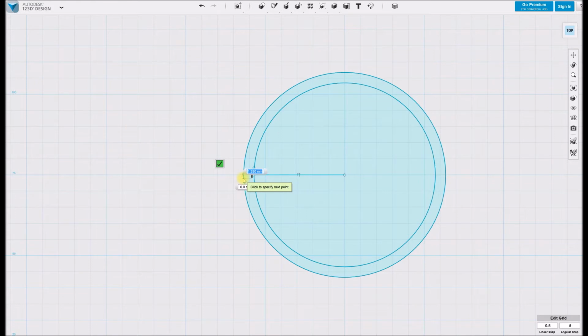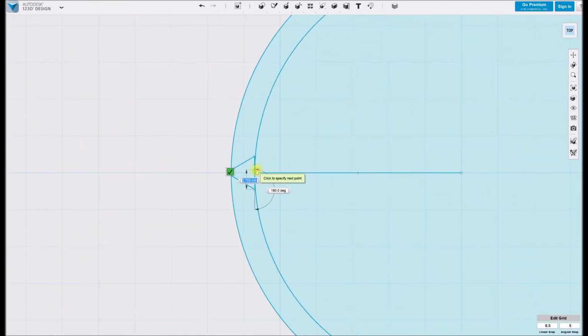So this dimension here is 0.75, and we do want it to be 0 degrees, so we'll go with that. Now it's 3.75 again, enter, and we want that to be 60 degrees, enter. So then we want to clear those again so it makes it free, and then we just tie it right back in again. You can see that that goes straight to 180 degrees and 2.25 millimeters. That's perfect. And you click. So now you can see we have our thread profile right here.